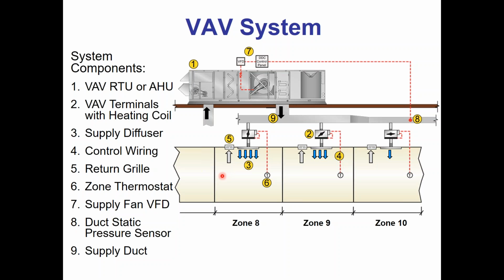Maybe you might put a thermostat in there and wire it into the controls of the rooftop or the air handler to only be used perhaps at night. When the system is off, you might be able to bring on, in this case, the gas-fired rooftop unit to provide some nighttime heating. And that can be done with a regular thermostat, in addition to the thermostats we have on the wall here. That's not very common because nowadays most of these VAV systems are DDC controlled, meaning all these boxes are networked together. So instead of throwing another thermostat on the wall that's hardwired to the rooftop for nighttime heating, we would just look at all the thermostats that are already in the space on the building automation system. And if those guys as a group started getting cold, we might do some nighttime heating. So you would not have to install any extra stats.